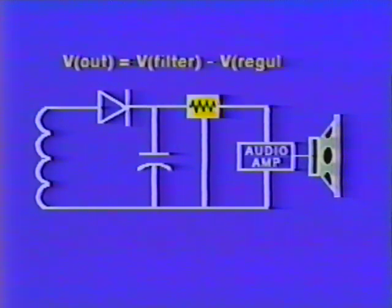A regulator follows the filter, as shown by the box here. It basically serves as a small variable resistance in series with the load. Since it acts as a resistance, the regulator has voltage dropped across it, and the output voltage is the difference between the output of the filter and the drop across the regulator.